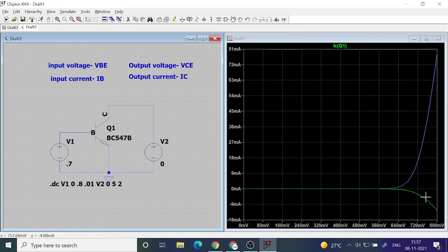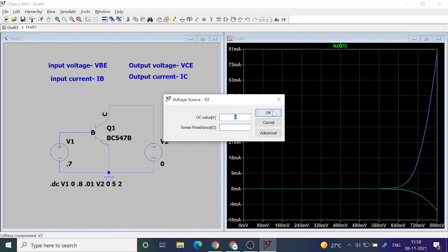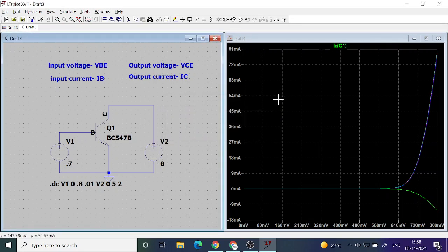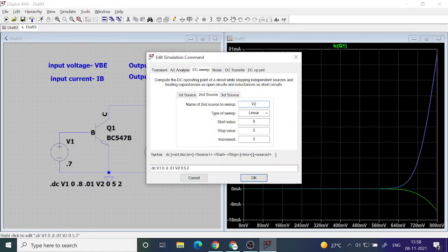There is some minus 9 milliampere. Now you can see it is close to minus 9 milliampere. That's at the edge. Okay, usually we don't operate the device there. We make sure that this voltage is at least above 0.2 volt or 0.3 volt. So that is why I avoided that point initially.